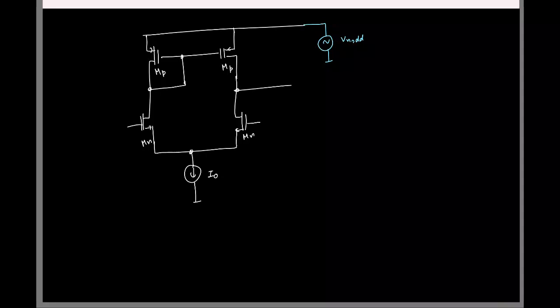Yeah, we can find the short circuit GM and the output resistance, right? So we don't have any other inputs. In small signal, the current source is open. So we can try to find the small signal GM and R out. I mean, you can also draw the entire equivalent incremental circuit and solve it.